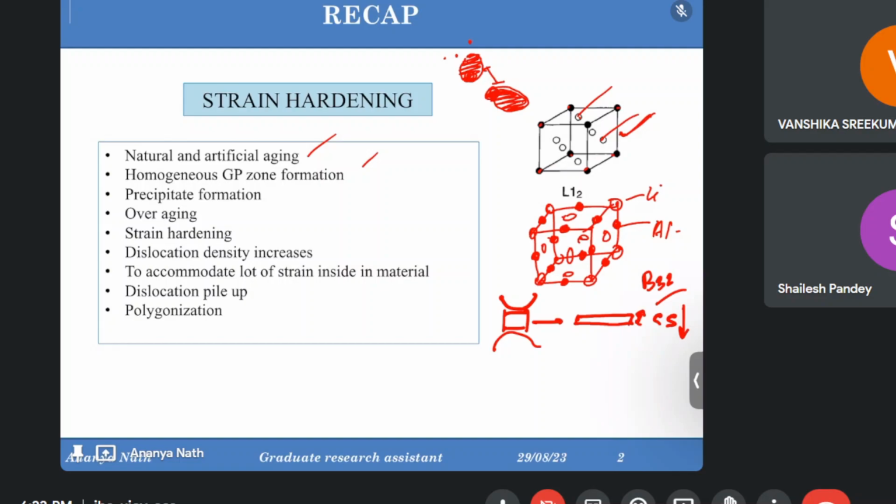As for substitutional solute atoms, the solute atoms need to have a nearby vacancy to jump into after having a certain level of activation energy. Similarly, for dislocations, they can easily move because there are a lot of slip systems. But if the lattice does not have that many slip systems, then the dislocations will also face difficulty moving forward. For FCC, it has the 111 direction, which has the slip system. So if the dislocation is facing that particular direction, then only it will move.